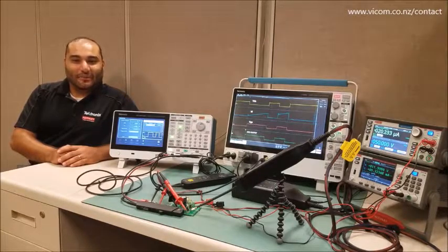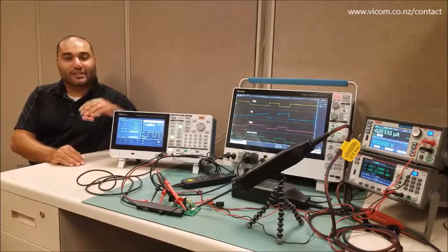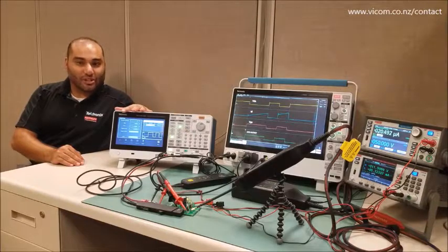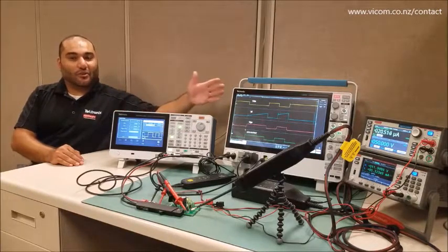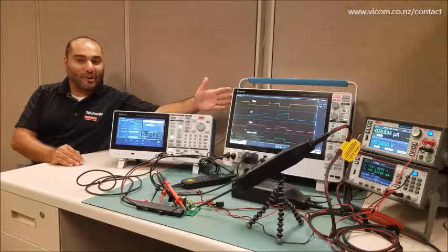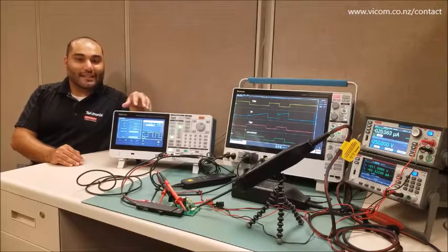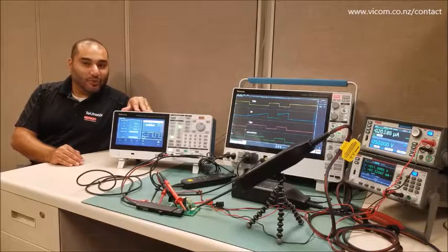Today, I'll explain what the double pulse test is and why engineers perform it. I'll show you how to use the double pulse application on a Tektronix Arbitrary Function Generator AFG31000 to set up your pulses in less than a minute. We will also show measurements on a Tektronix Oscilloscope MSO5 to measure our parameters. We will be doing this test using an ST micro eval board, a Keithley SMU, and a Tektronix IsoVu probe, a current probe, and a differential probe.